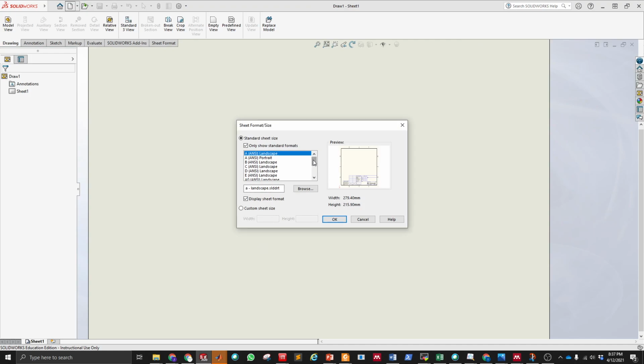And for this one, I'm gonna use the A2 landscape, this size for the sheet, and then click OK. So as you will see, A0 is the largest one, and as you increase the number, they become smaller and smaller. Here we have the width and the height. So for this homework, I'm going to request A2. I think that's enough space for doing what we have to do.